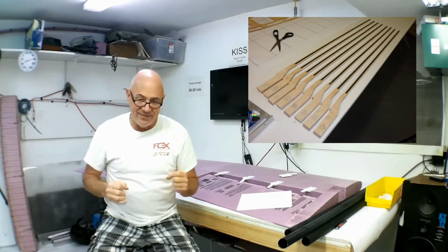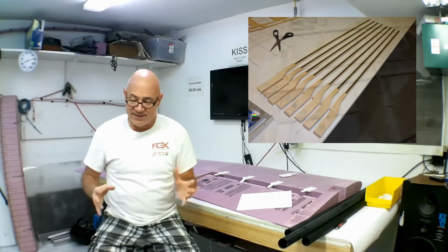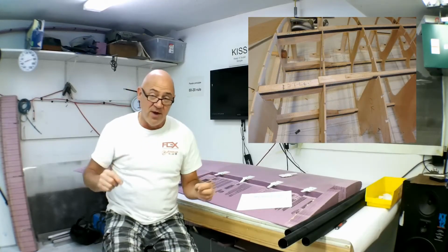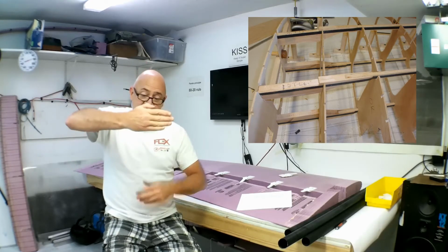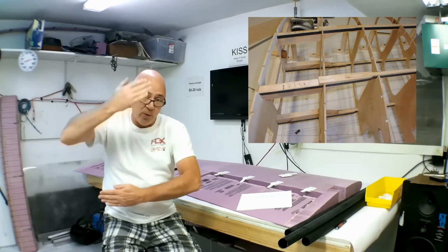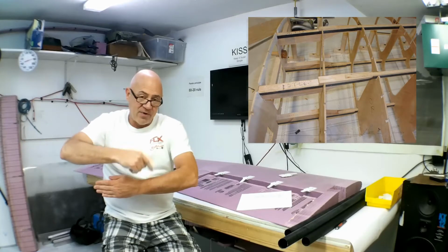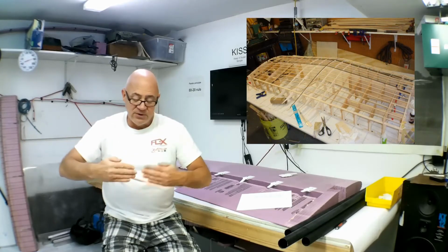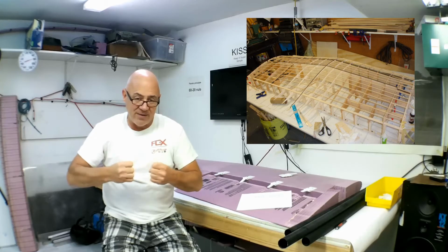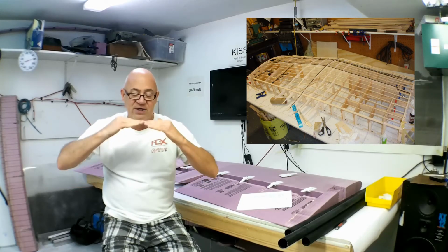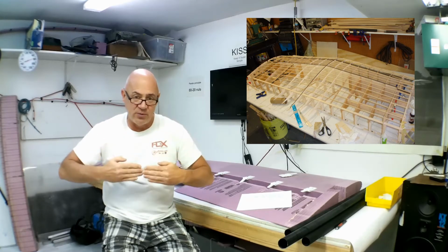Well, it might, but I couldn't get it to stretch in any of my testing. I used carbon fiber tow pre-impregnated with fiberglass. So I've got a top spar, a bottom spar, and a shear web between them. I never thought about compressibility. When balsa wood is soft and compresses, that carbon fiber is not in tension.